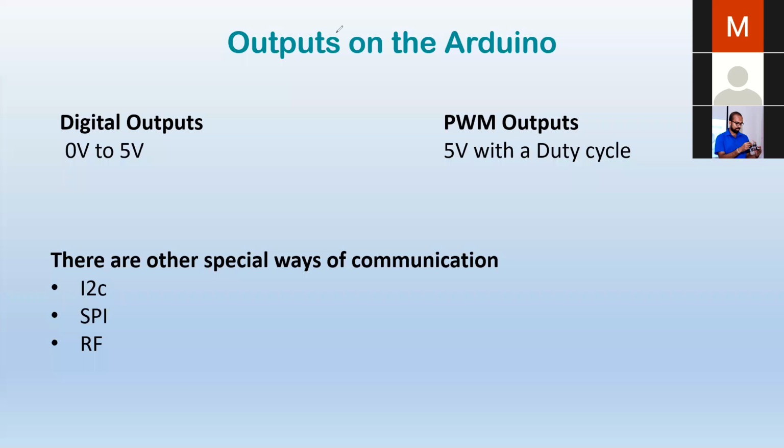So, you can write code like this, right? If you want to read a pin, you can write digitalRead pin 3, right? This is going to read the state of digital 3 and give it to you. It is absolutely fine, but there is a drawback to this, all right? The thing is, the Arduino is constantly going to check the state of the digital 3 pin, and sometimes you don't need to do that. So let me tell you that with an example.